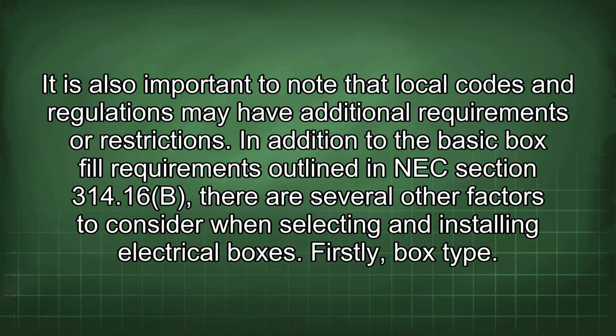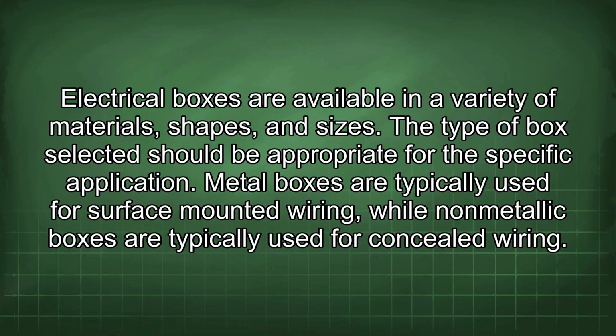In addition to the basic box fill requirements outlined in NEC section 314.16(B), there are several other factors to consider when selecting and installing electrical boxes. Firstly, box type. Electrical boxes are available in a variety of materials, shapes, and sizes. The type of box selected should be appropriate for the specific application.